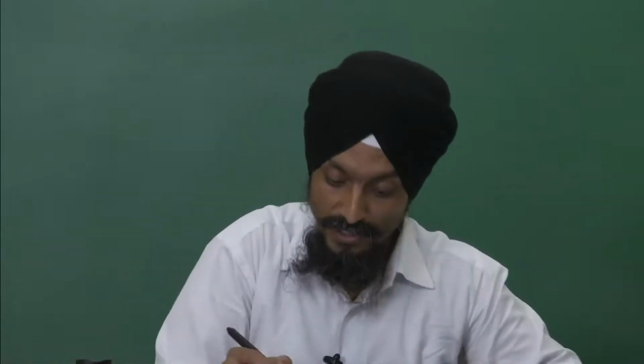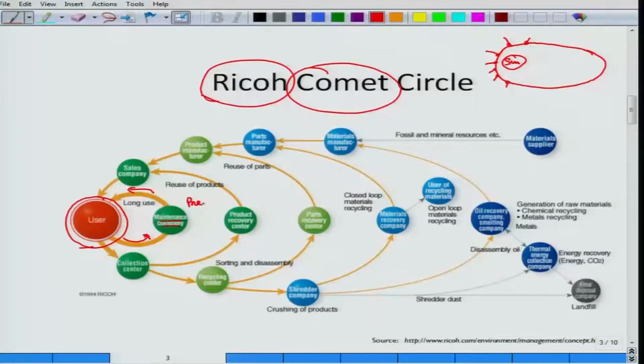The company asks you to do the first service in the first 2500 kilometers, then in 5000 kilometers, then every 2500 kilometers, or in 3 months, maybe in 6 months. So, this is known as preventive maintenance, that is, prevention of any breakdown or stopping of the bike.